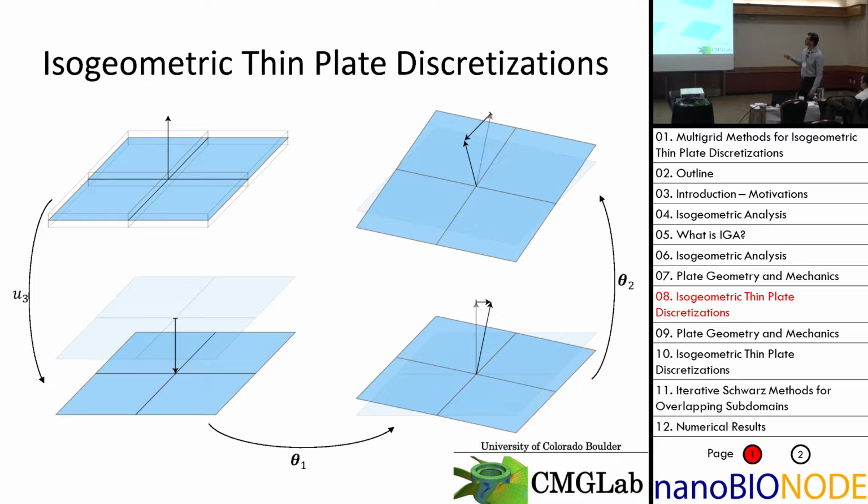So this is a crude idealization of the deformation modes associated with our plates, and what we'll later define as our subdomains when we're smoothing through our V-cycles. Essentially what we have up here is an undeformed plate. And it's a little difficult to see on this projector, but the thickness there is kind of translucent, and we have the mid-surface, and then this is our normal vector. So the first displacement mode would just be translational. So we basically shift this plate down. This is just the translational effects to loading something on the top.